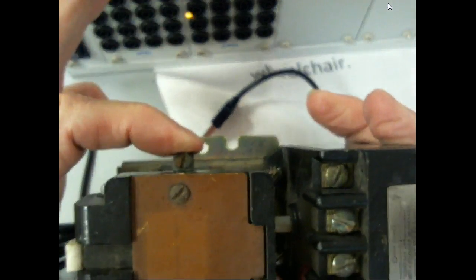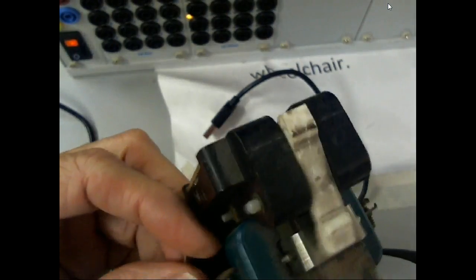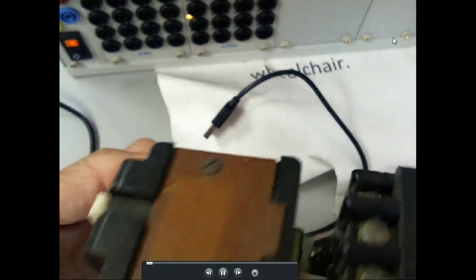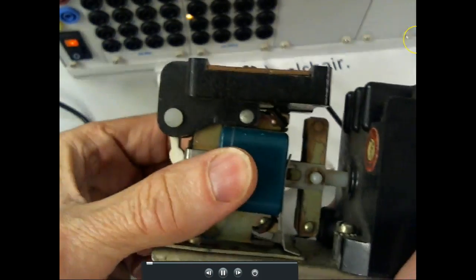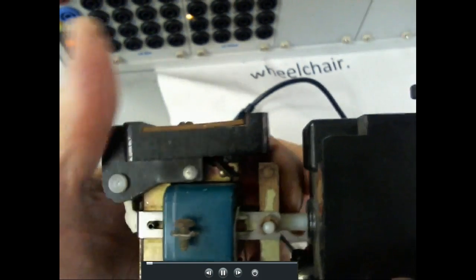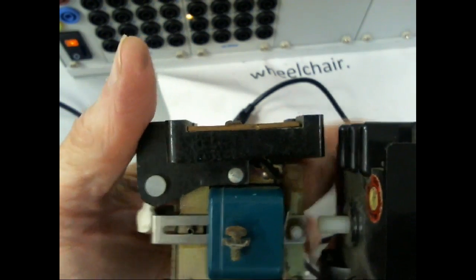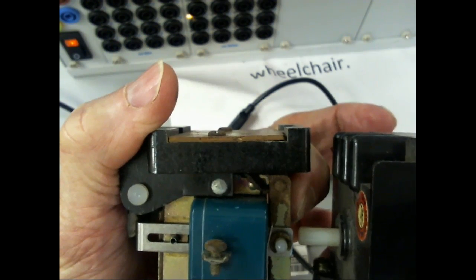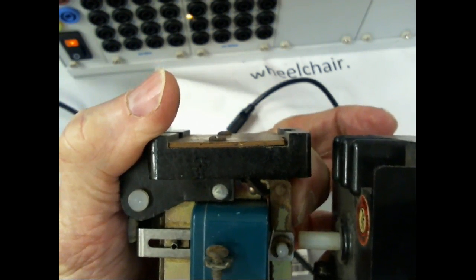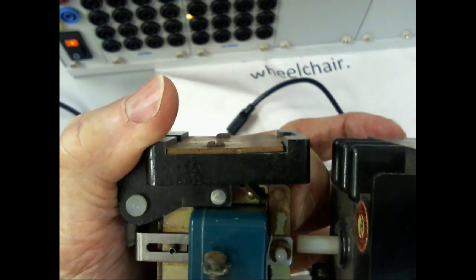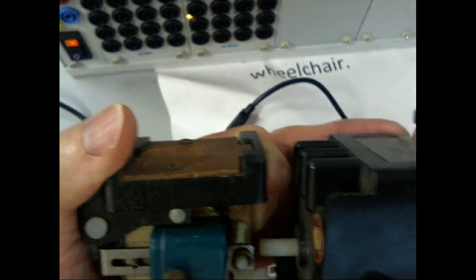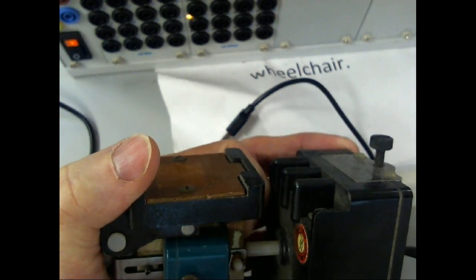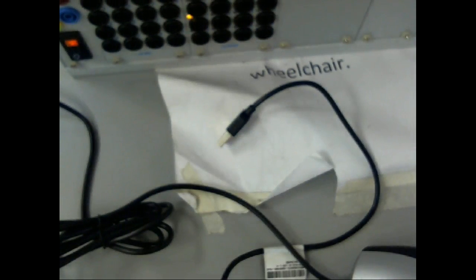And then when I put whatever's required by this coil right here, this is a 110 volt coil. So it's an AC coil. I put 110 volts across here, then it would cause the solenoid to pull in, and then you can see it start doing what? Yeah, because it's turned down pretty. And then sooner or later the contacts change, either all your normally open would change and your normally closed would change, right? Does that make sense?